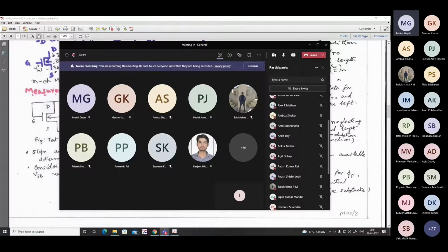Because if we increase the drain voltage, it automatically increases the gate voltage also. Exactly, very good. As gate and drain are connected together, however high you make the drain to source potential, the gate potential is also correspondingly increasing. So it is not possible to take the transistor deep into saturation and allow for a sizable slope for the current.